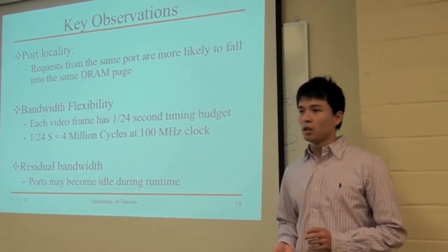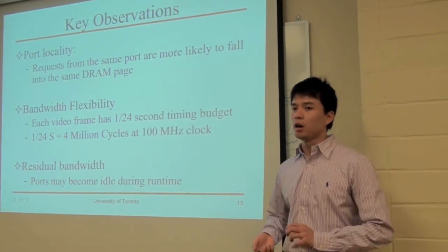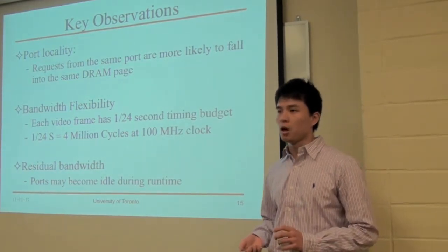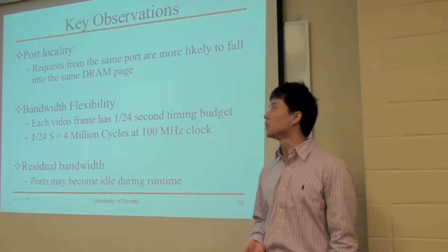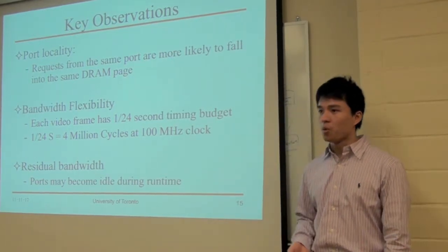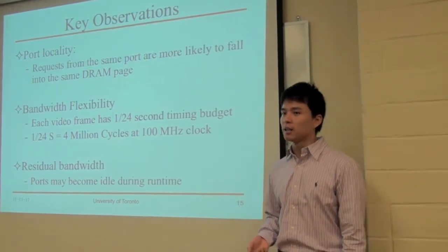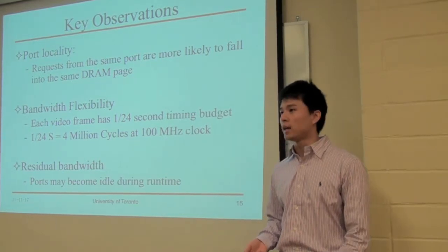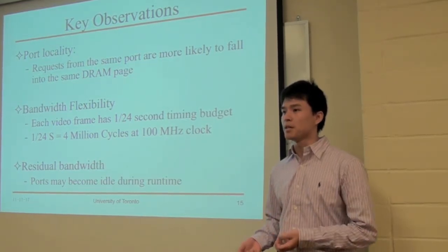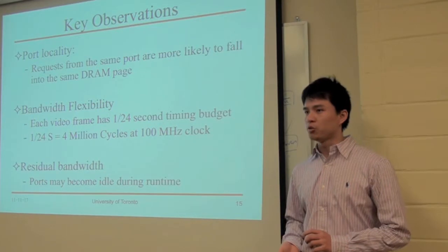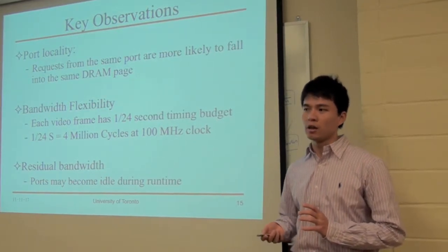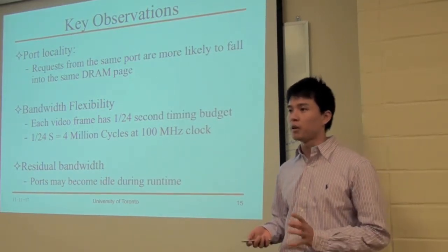So in order to meet all the objectives, we try to leverage three key observations of MPMC designs. The first one is port locality. We think that requests from the same port are more likely to fall into the same DRAM pages. The second observation is that the bandwidth guarantee can actually be very flexible.